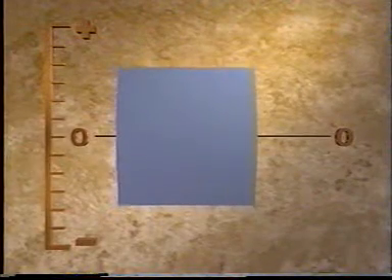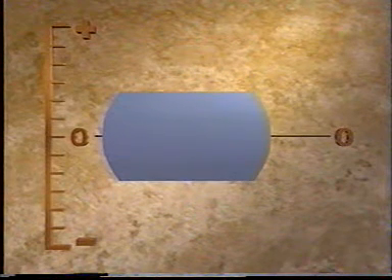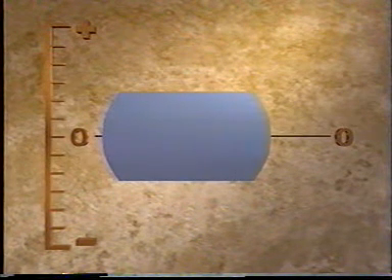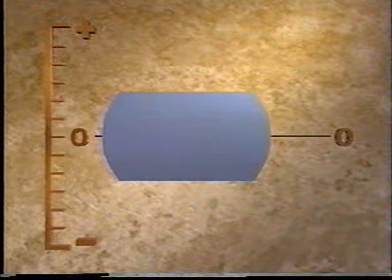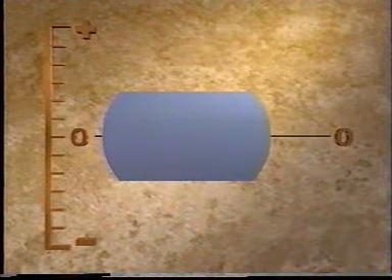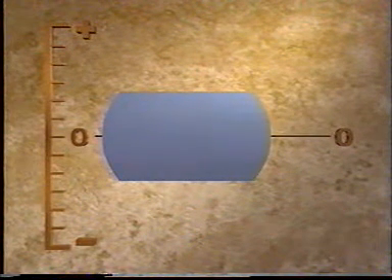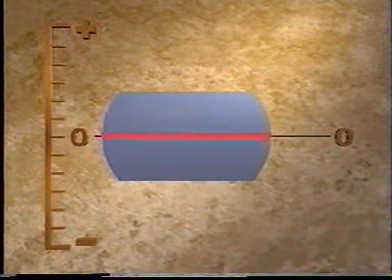Ductile metals do not fracture in compression, simply because the metal is being squeezed, not pulled apart. The metal yields or bulges rather than fractures. Yielding is the normal mode of failure in ductile metals under compressive stress.